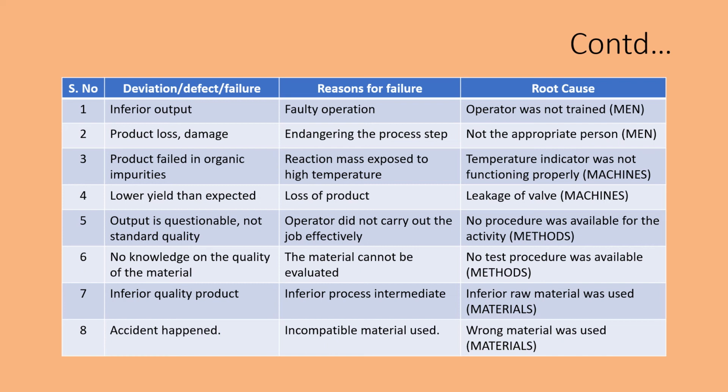Product failed in organic impurities because the reaction mass was exposed to the high temperature. This is the reason for failure. What was the root cause? The temperature indicator was not functioning properly. Low yield than expected. The reason was there was a loss of product. This happened, the root cause was the leakage of valve.